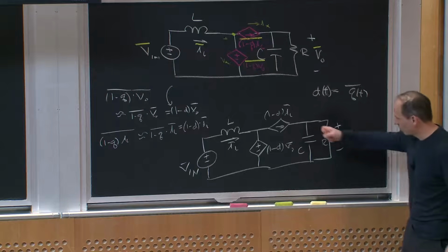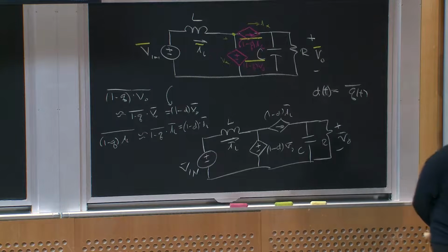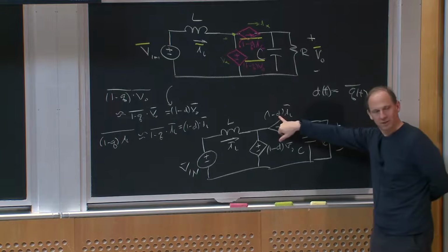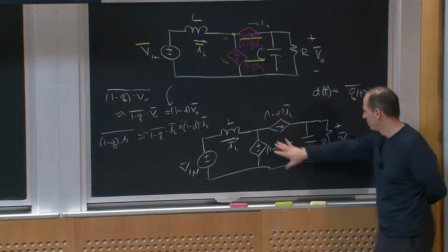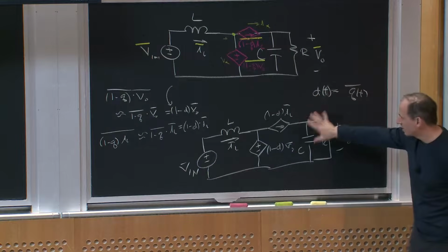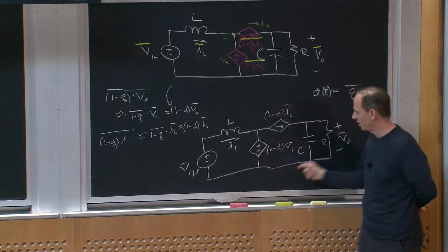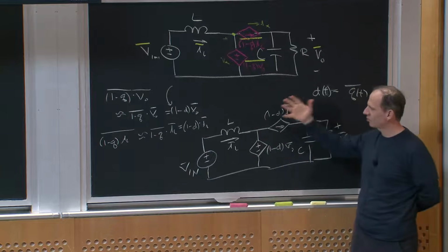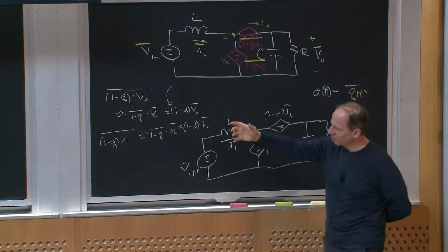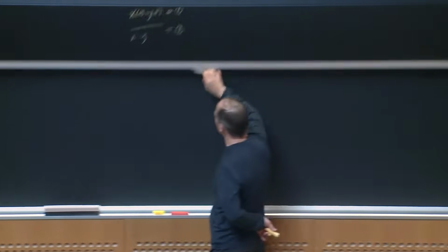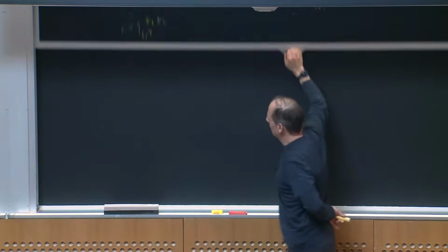This circuit has no switching. D is a continuously varying variable that my controller might generate. It does vary in time. It's a dynamic circuit with an L and a C, and if D changes over time, the voltages and currents will change, but I've killed the switching ripple, essentially applying my local average operator to the circuit.